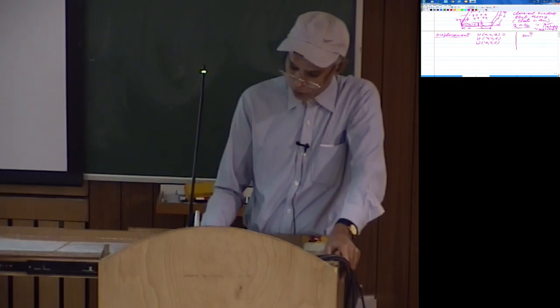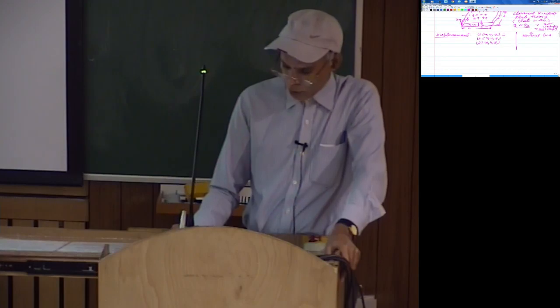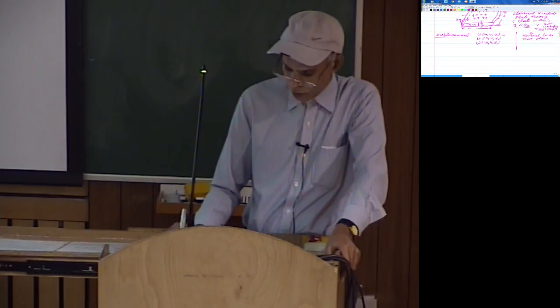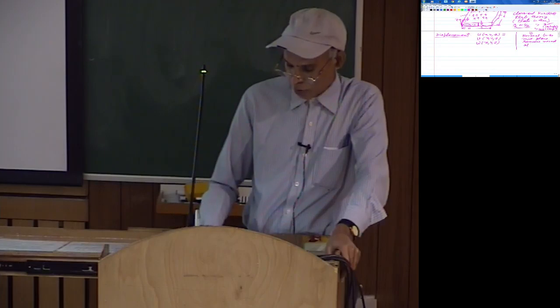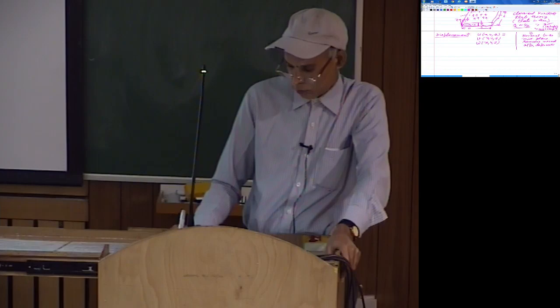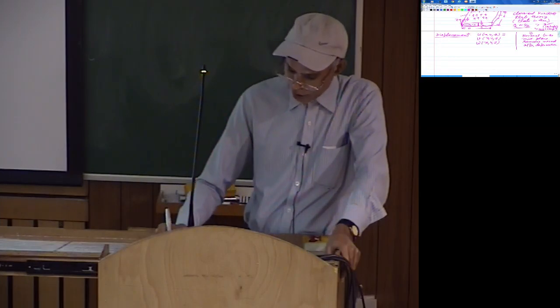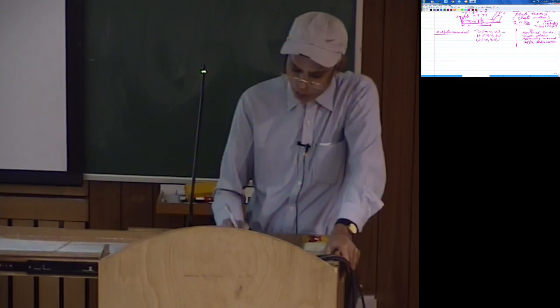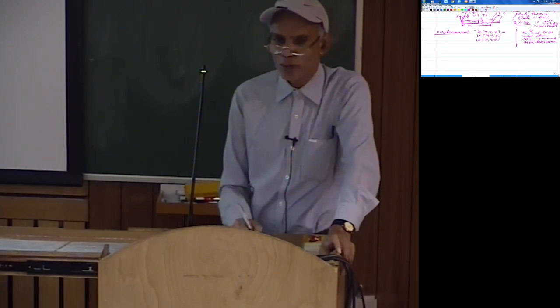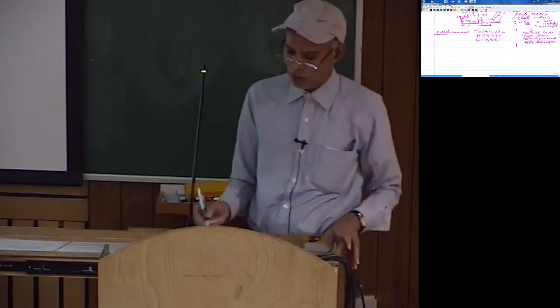So normal to the middle plane, mid plane, remains normal after deformation. So that now using this, we can express the in-plane displacements u and v as a known function of z, that is, a linear function of z.